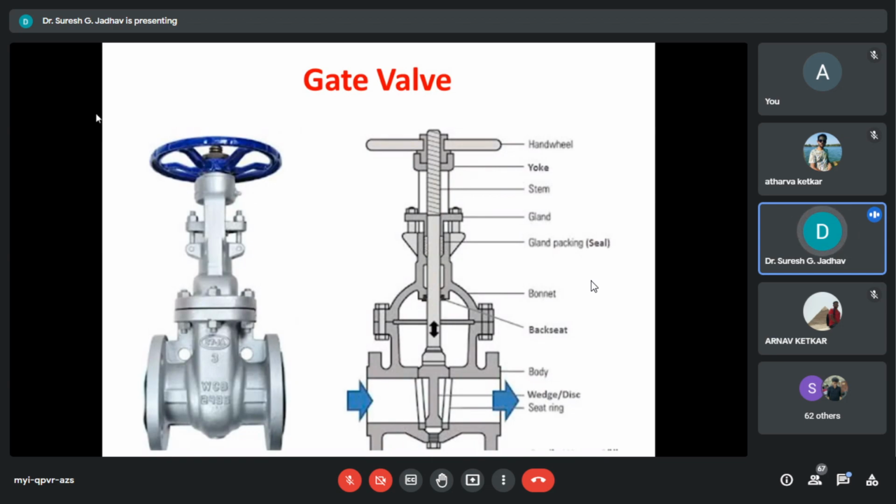In two piece design, there will be a gland flange and follower. The follower will have a spherical end which facilitates proper alignment of follower and loading on the packing. In single piece, the gland and follower will be integral.